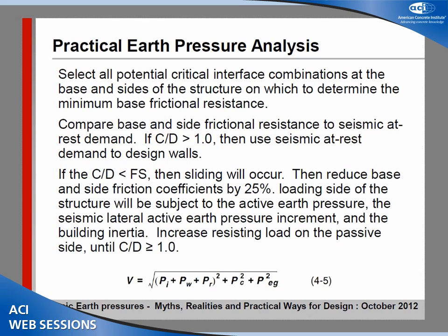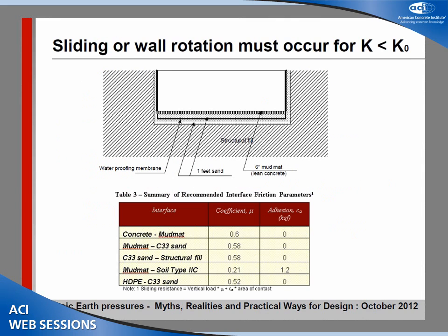And then to calculate these very different terms that appear in here, the code does provide guidelines. Okay, you are going to do the stability analysis. You have to pick where the different interfaces along which the structure could be sliding, and then you have to calculate the different forces acting on the structure, forces due to fluid, forces due to earth pressures.